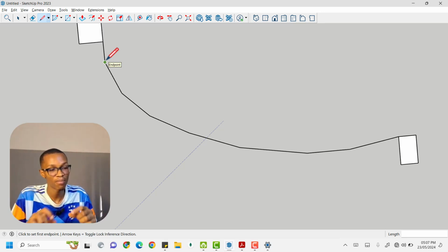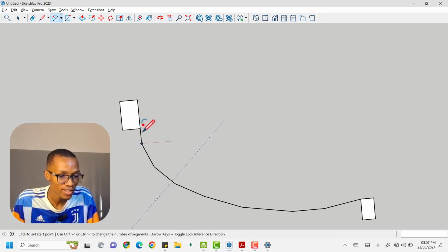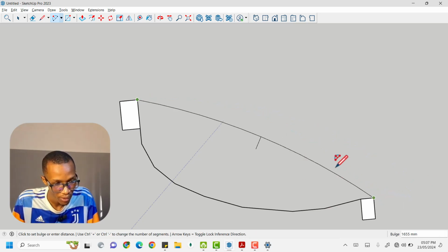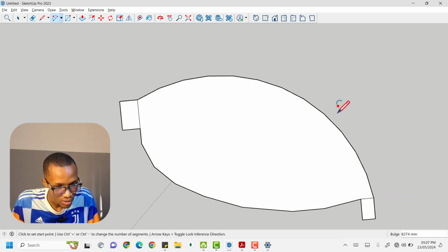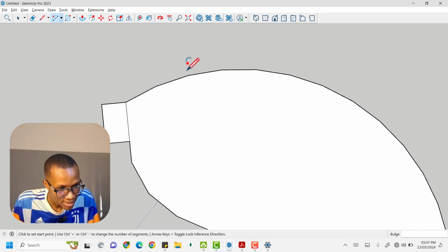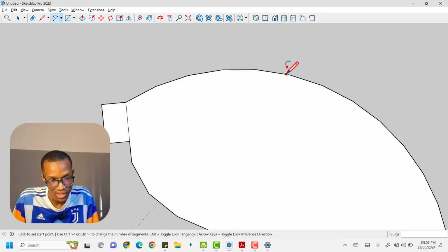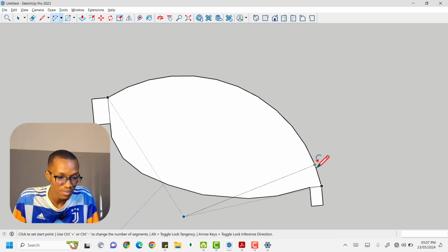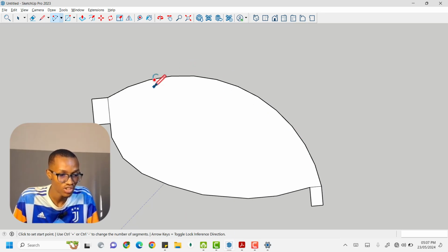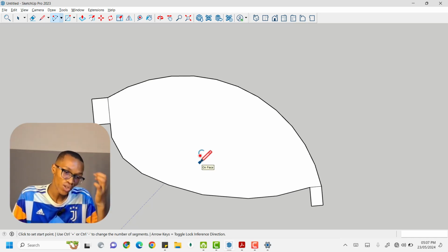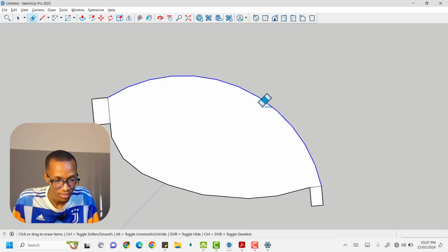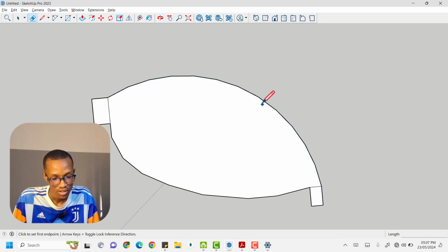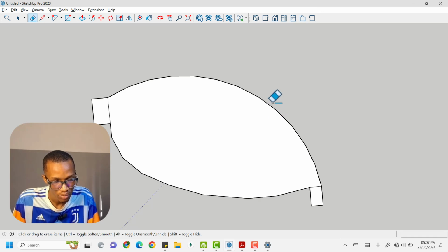So if I show you carefully, if I go back to the arc tool, let's say I have the 2-point arc tool. I want to join an arc from here to this point. Now, do you notice that when I draw the arc, there are sharp edges? You can see those sharp edges. Those are the sides. All right, so what that means is this arc is made up of various lines that are joined together, and those lines are actually what makes the arc. It's grouped together, so if I were to use a pen tool to break that, I couldn't break that.